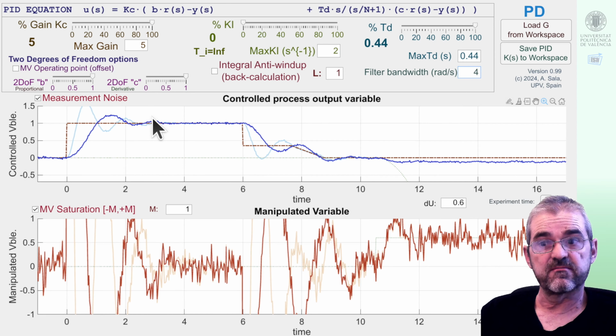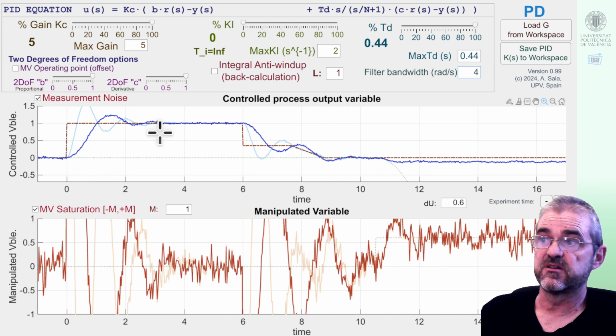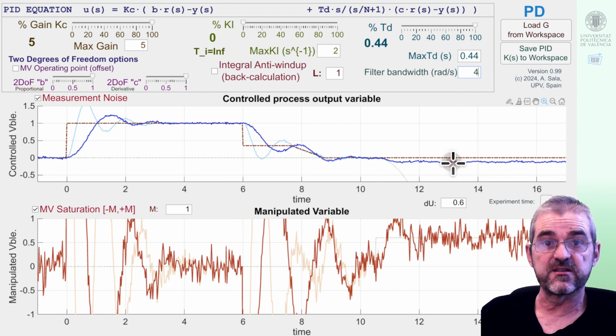So one thing is passing my examinations, but in real life, we need to think in which are the sensible requirements that can indeed be achieved given my force limitations and my non-ideal sensors that have some noise that needs to be filtered. Then if I require slow enough specifications, then theory and practice will be similar. If I require specifications with too high gains, then theory and practice will be very different. So in fact, in here, my problem was the excessive gain needed to make this error small.